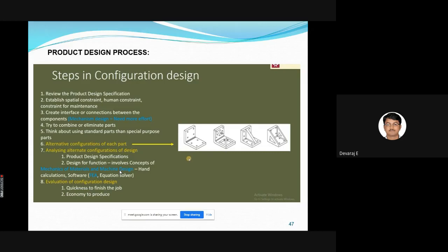So create this bracket, apply the TV load on the bracket, and find the stresses for all the four different brackets. Can anyone tell me for which bracket you will get the less stress? Sir, I am not sure, but I think it's the second one, sir, because they have removed the sharp edges, so stress concentration will be less in that. Okay, good, Sachin.